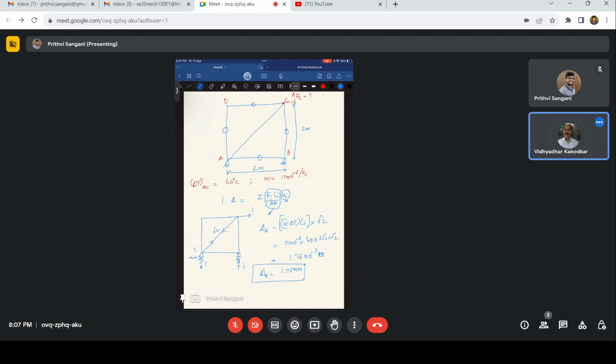And the second one is, what if the member is too short or too long? Sometimes it can also be long. So you will compress it and then tighten it at the gusset plates, and it also induces some kind of displacements or extra forces which are not actually intended, but are forced into the members.